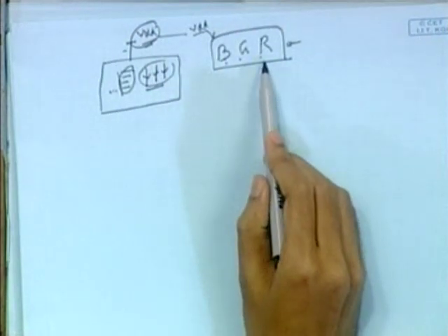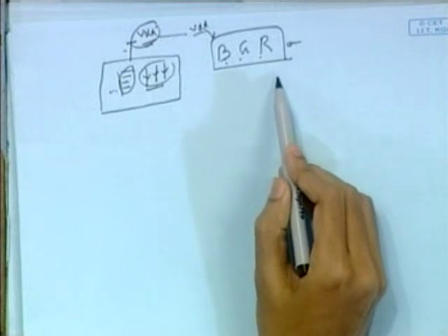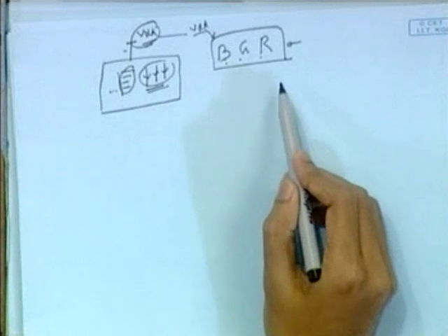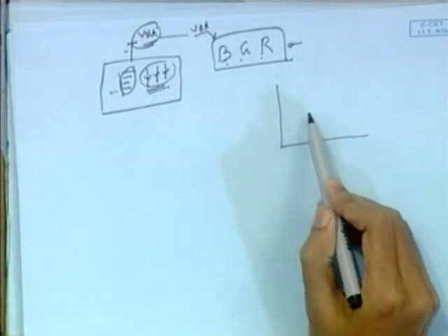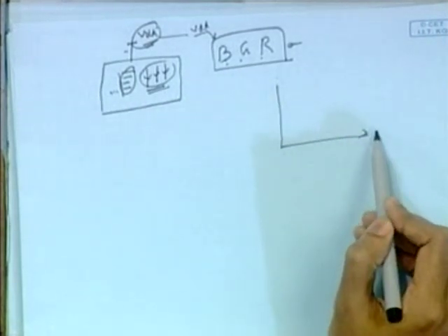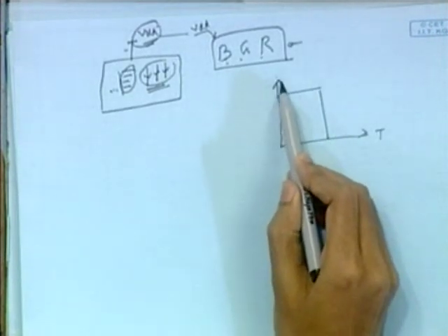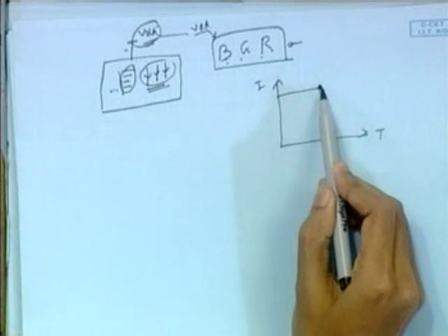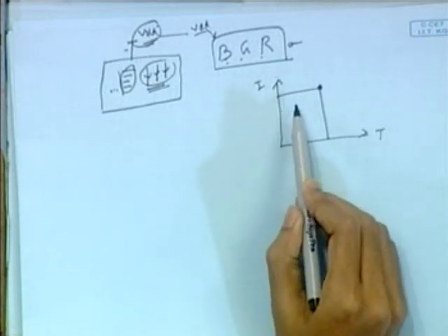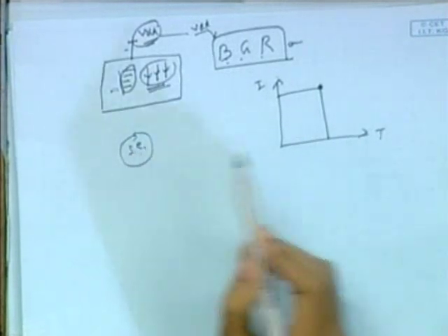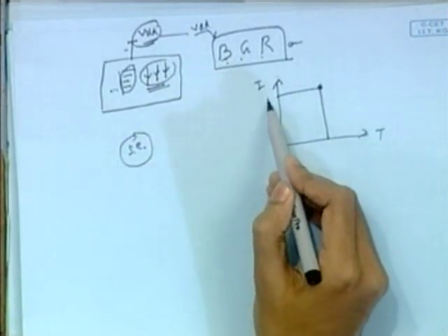And also we can incorporate the temperature insensitivity of these currents or voltages. I mean, if you vary the operating temperature of the chip, the IC, this is the temperature. Suppose this is your designed current. You are plotting current here. This is the value of current for which you have designed your IC, a particular subcircuit, call it SC, designed for I0.